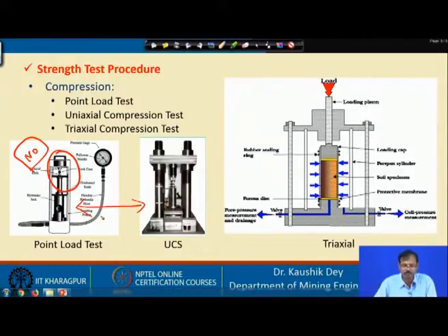In the compressive test, the problem is the preparation of the sample, where great care has to be taken on the smoothness, dimensions and linearity of the samples. This care should be taken prior to carrying out the test.